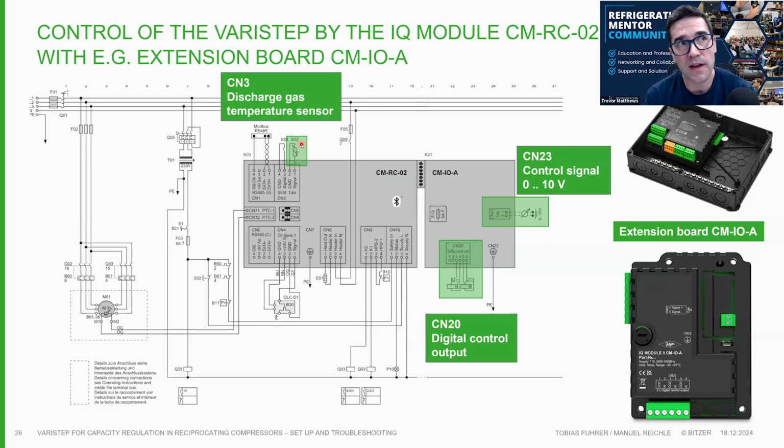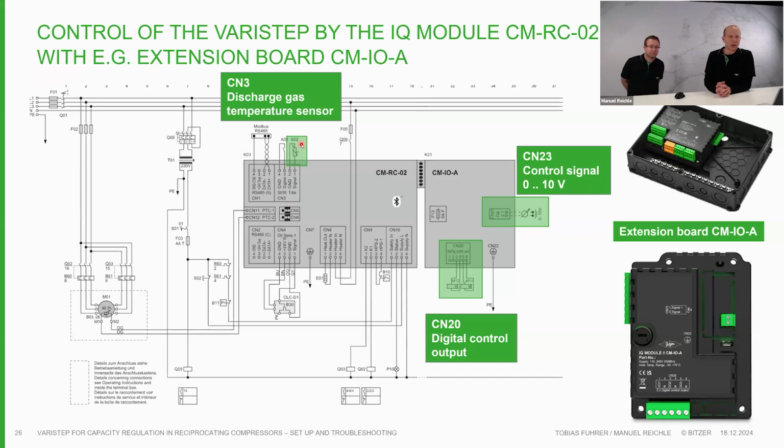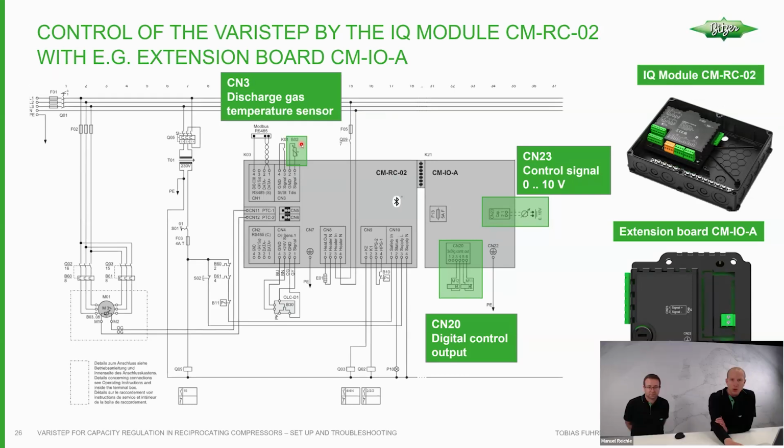Does it go in the head of the compressor? Is that where it would go, on the right side, or what side? In the common discharge flow, let's say. So after the cylinder head, but in some cases before the discharge shut-off valve. Yep, makes sense. Good.